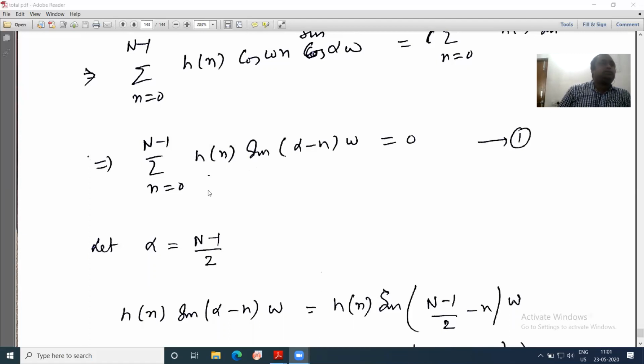If it is multiplied by some constant, say 2, I can multiply by half again so that I can get the amplitude of this signal as desired. Therefore, if a signal is multiplied by some constant and shifted by some amount, this is not changing the basic characteristics of the signal. And this is desired, because filtering is a process by which we extract the desired part of a signal. This is the basic characteristic of a filter.